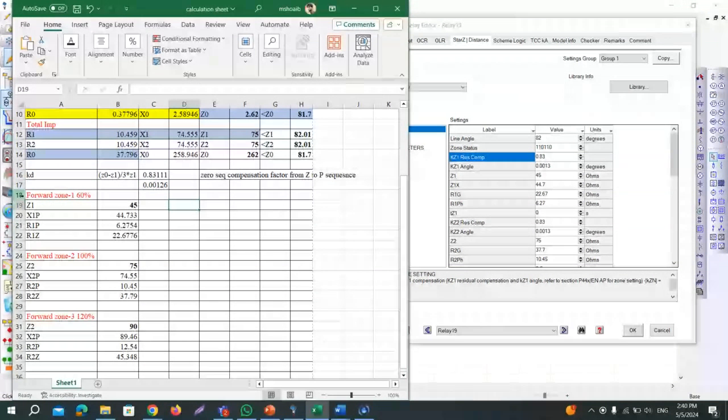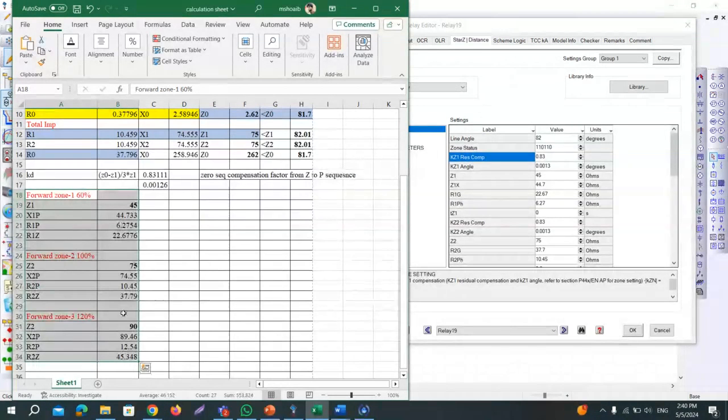After that, just have a look here. I have put some information. This Z1 is the positive sequence impedance, real value. X1 is the positive sequence reactance, R1 the positive sequence resistance. This one is zero sequence. This Z is the zero sequence resistance. These pieces of information I have taken from here. You see this blue highlight, blue highlight, blue highlight, blue highlight. So these 4 data are taken over here. Now why have I extracted this data?